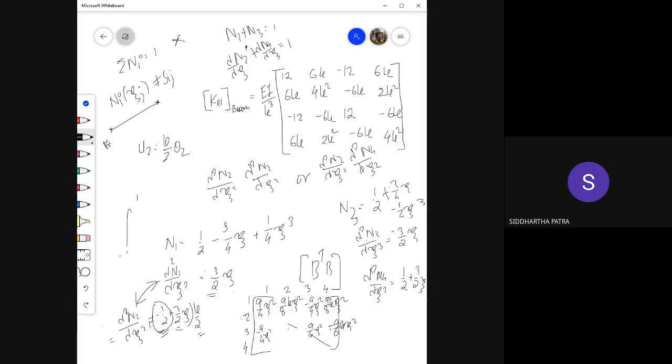One is the regular value of the shape function. The other one is the derivative of the shape function with respect to xi. If you think in this way, then actually this second rule applies. Now, having said that, this is what the element shape function must look like for the Euler-Bernoulli beam element.